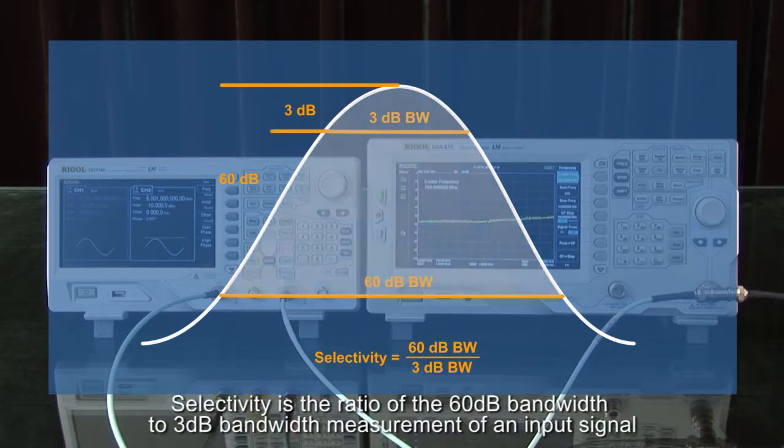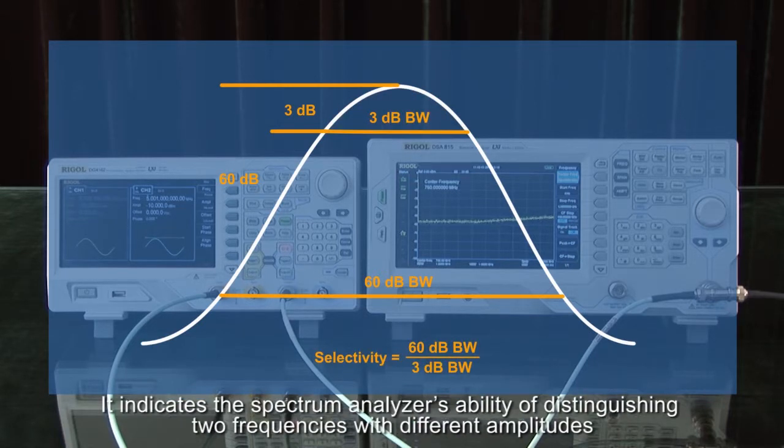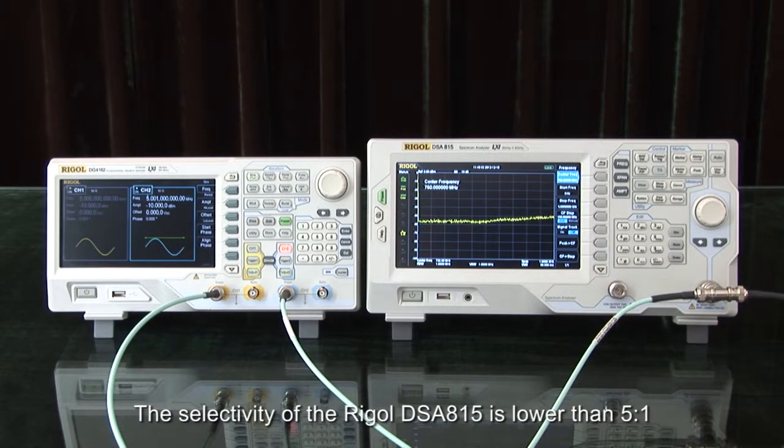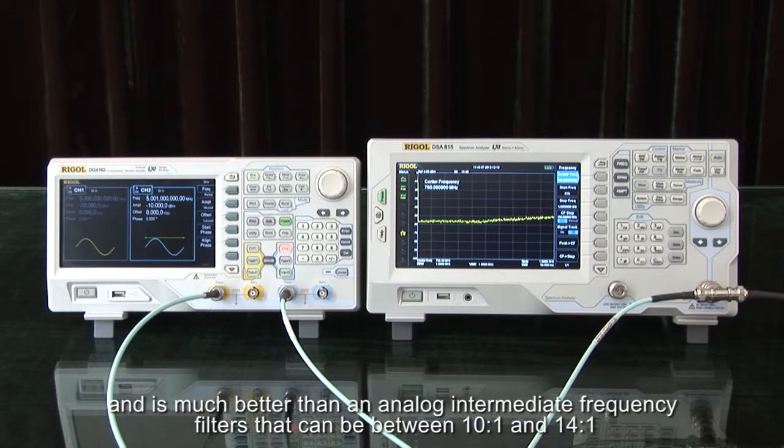Selectivity is the ratio of the 60 dB bandwidth to the 3 dB bandwidth measurement of an input signal. It indicates the spectrum analyzer's ability to distinguish frequencies with different amplitudes. The selectivity of the DSA-815 is lower than 5 to 1 and is much better than an analog intermediate frequency filter, typically achieving 10 to 1 or 14 to 1 ratio.